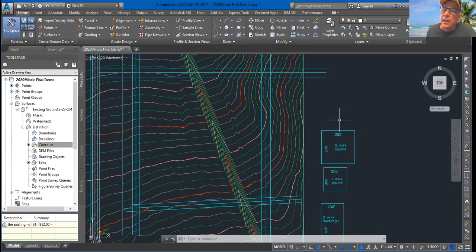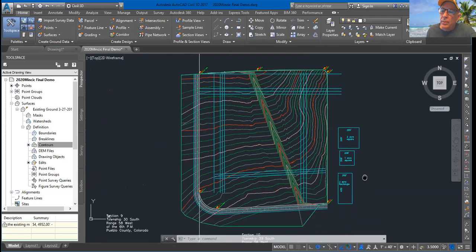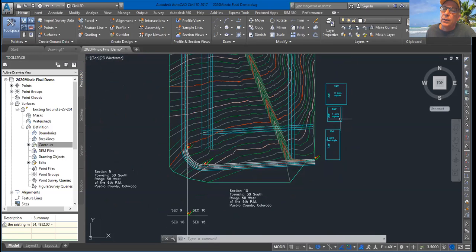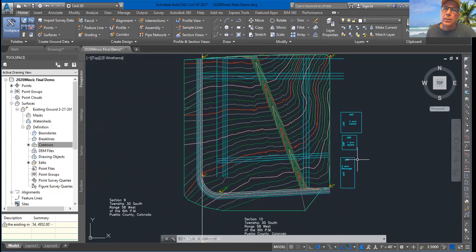I also have a rectangular 2 acre parcel here. Simply take the 43,560, multiply it times 2, and take the square root of it, and you'll notice that a 2 acre square parcel is 295 feet by 295 feet. Also down here, I did something that's a little bit different, where I have a larger, more rectangular lot where it's 200 feet across the front and 435 feet deep. That's also a 2 acre parcel, but you notice that we get our 2 acres, but in a different sort of configuration. The reason I like to do this is it helps me as a planning tool decide what exactly I would like to do with my parcels.